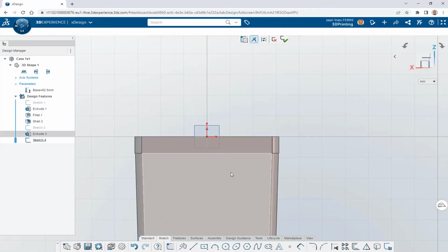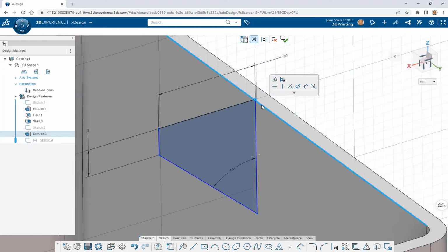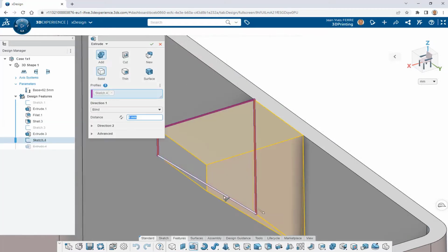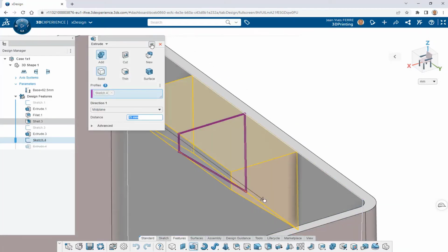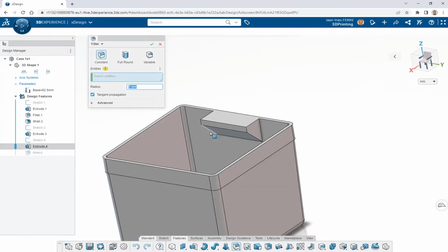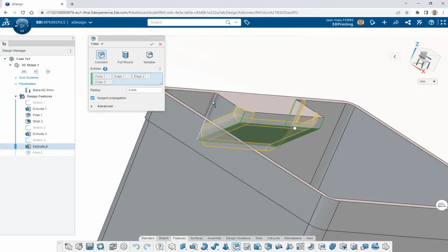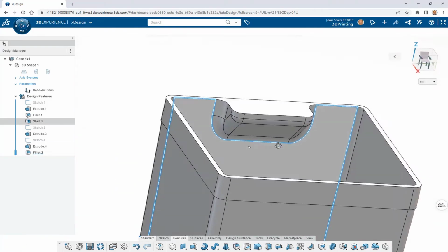Now I will create the label holder that will also be useful to grab the box inside the drawer. I select the right plane and draw my geometry roughly first. Then I refine it with dimensions. Then a relation on this vertex to force it on this perpendicular edge. When sketch turns black, it's fully defined, so further changes on the model will update the part without errors. I extrude the sketch midplane with a total width of 25 mm and add 3 mm fillets as shown.